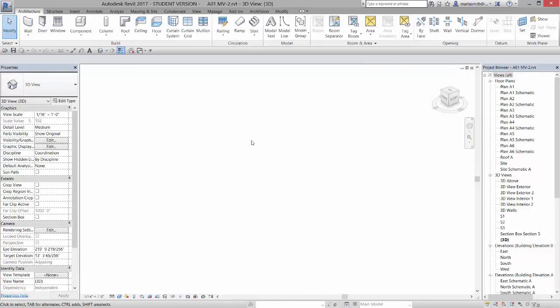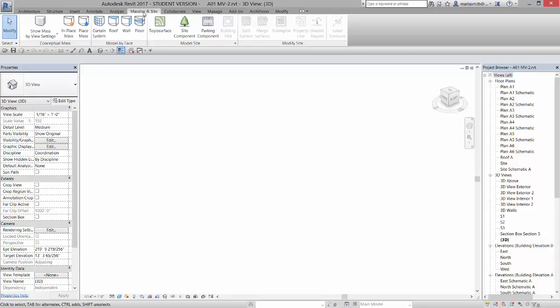And it's going to show nothing. The masses have been toggled off by opening and closing the Revit file. So let's turn them back on. I'm going to go to the massing and site. And right now it says show mass by view settings.